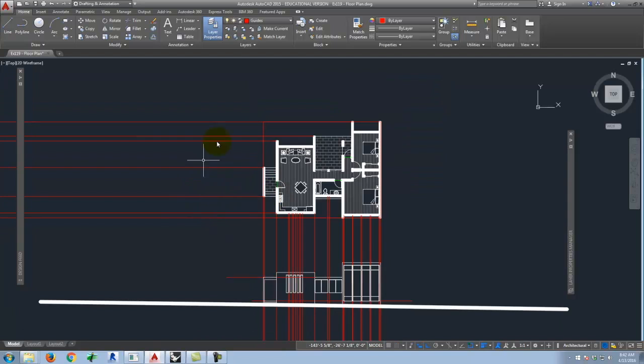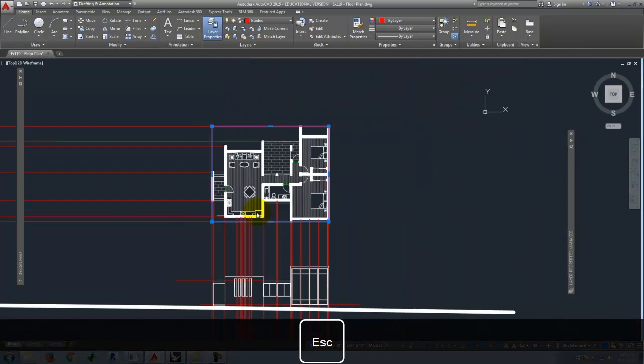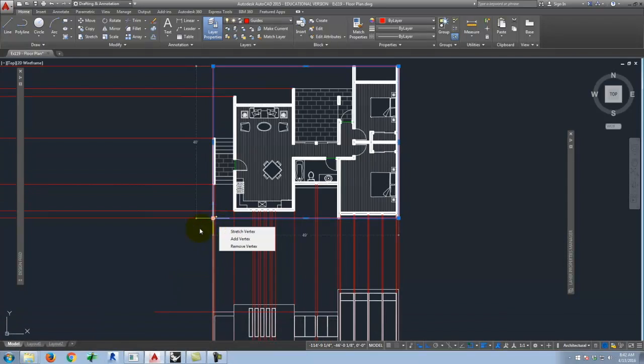So the other thing about these views is there is a relationship between this view here and the view that's going to go right here. And if you guys did 130 and you remember there was that reflecting line, you drew that 45-degree line. Do you vaguely remember that if you took 130? We can use the same principle here to help ourselves with heights. Okay? So what I'm going to do is I'm not going to go from this corner. I'm going to go to that bounding box that I created right here. And I'm going to do my reflecting line from that corner.